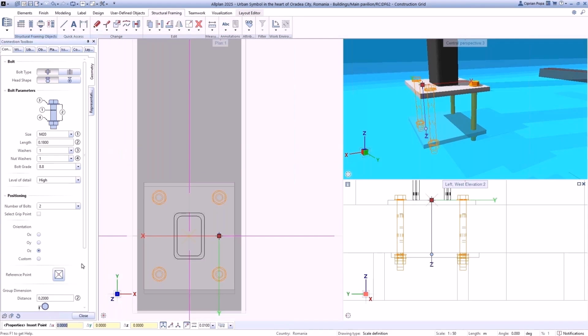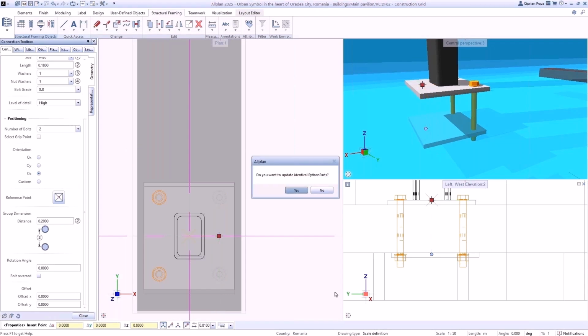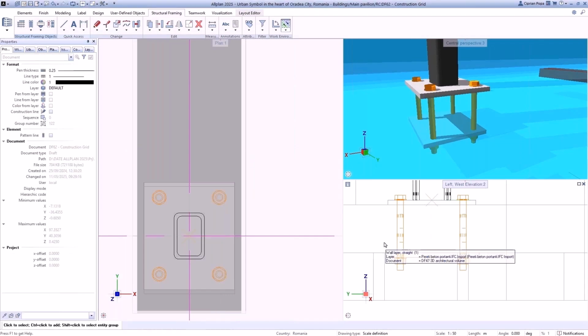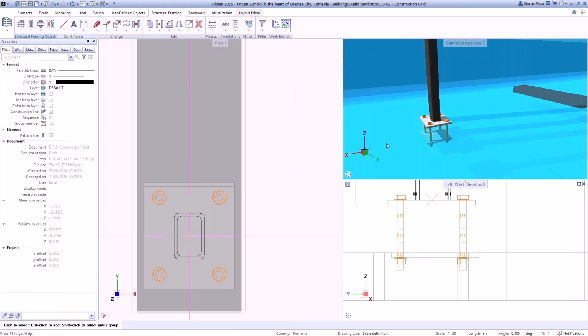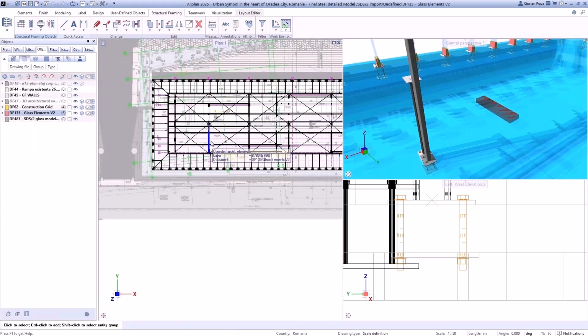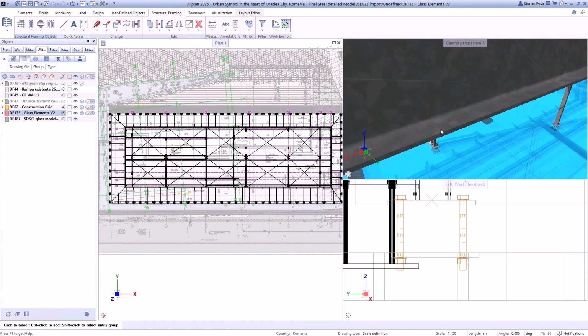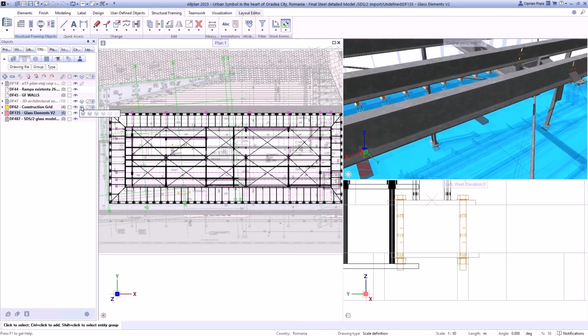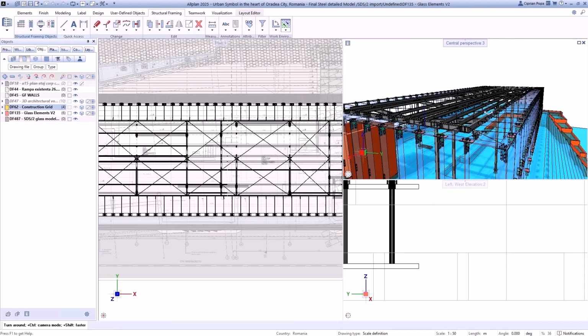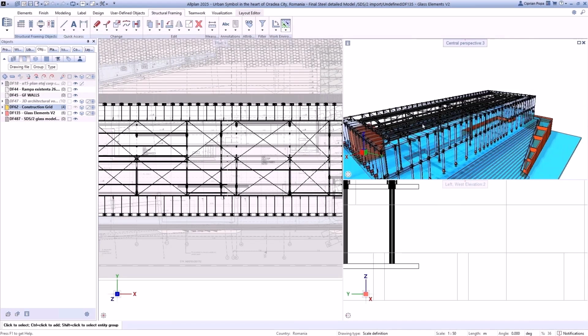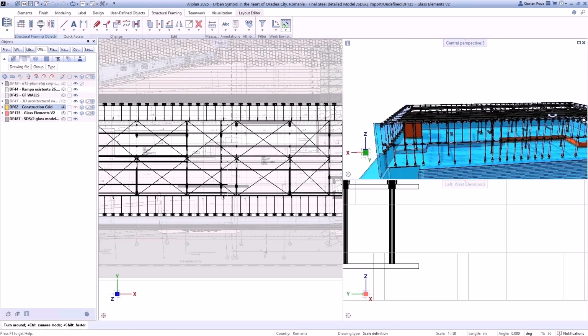You see, we're not thinking of any kind of coordinates. We're just trying to stay within the volume of the architecture and respect the existing infrastructure. And step by step, we can make a proposal of the steel structure as we would expect, making sure that in this case, the columns, one condition, were to be hidden by plasterboard non-structural walls.